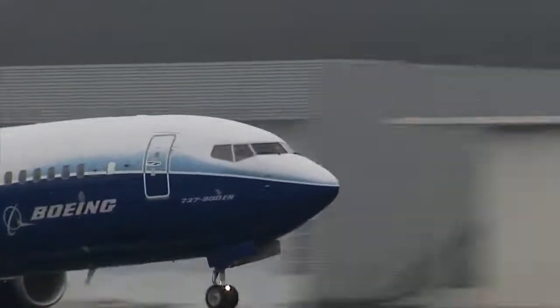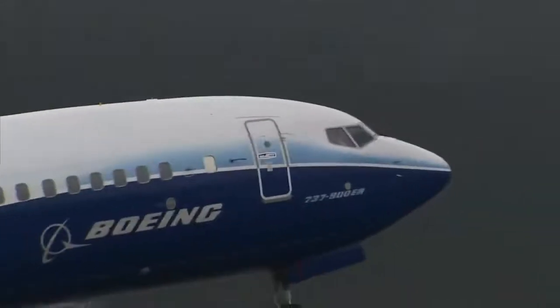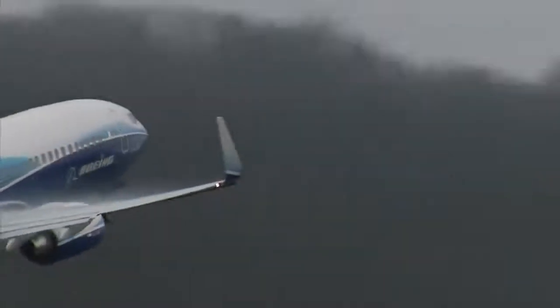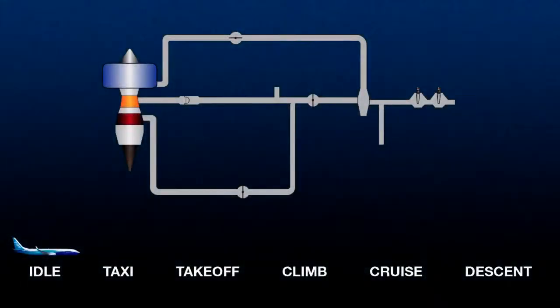Now let's see how the bleed air system operates during a typical flight. At ground idle, since the engine speed is low, the HSV is open and the system is running on 9th stage air. At these low pressures, the PRSOV is also wide open. The temperature is usually low enough that the PCCV is closed.